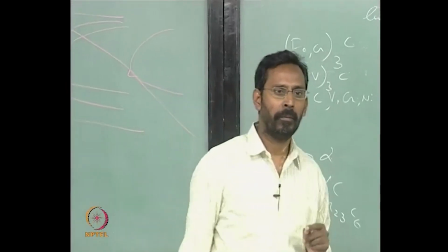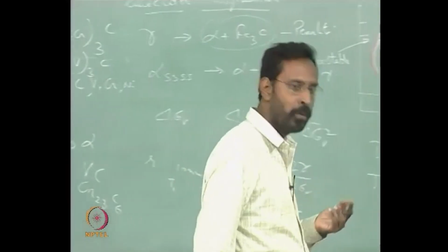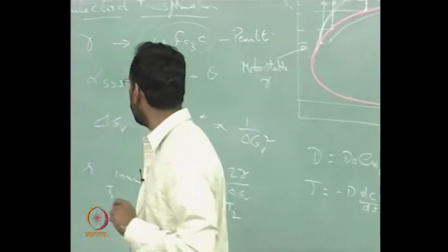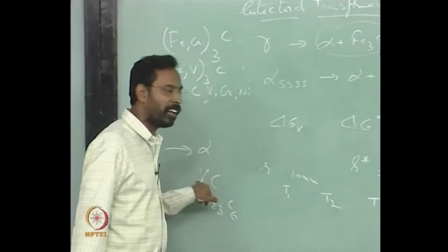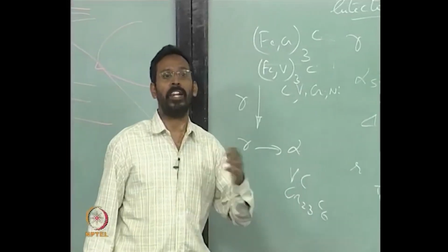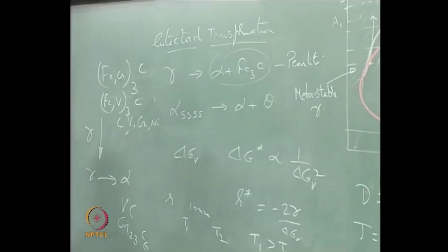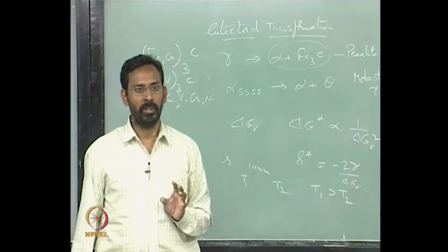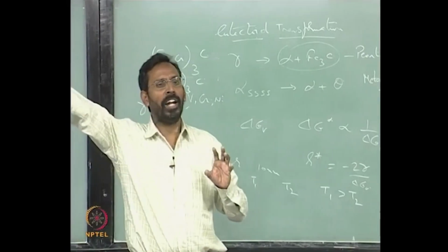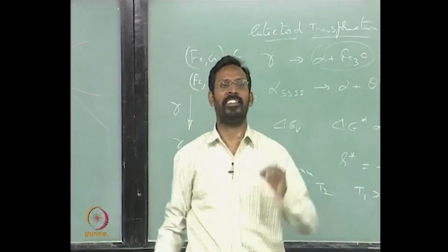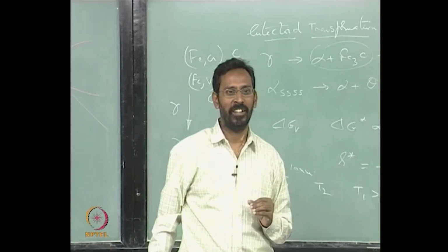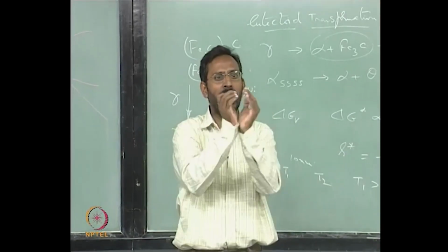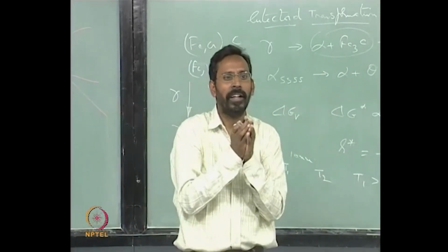Sir, the carbide may not be coherent with Fe3C. True, so that is important. If, for example, vanadium carbide or titanium carbide is available, obviously around that carbide the carbon content has come down. So it could not only nucleate Fe3C, it could even nucleate ferrite, because all the carbon inside the gamma in a small region has been taken up by the vanadium.